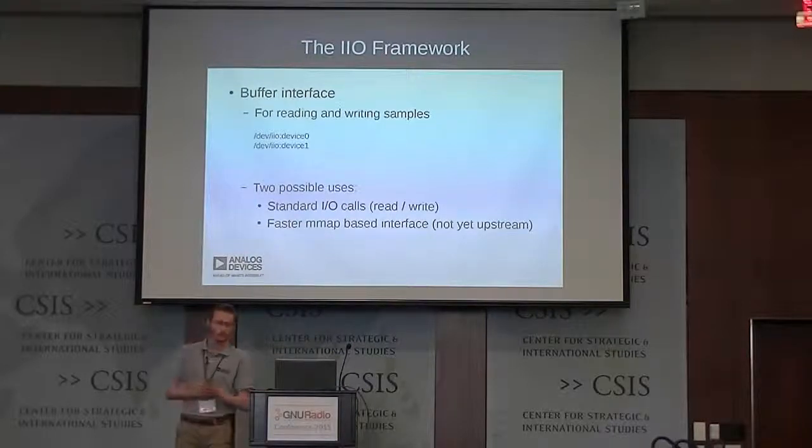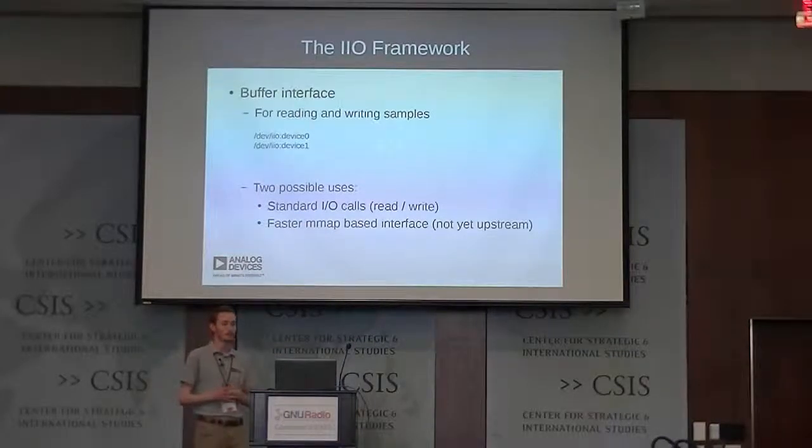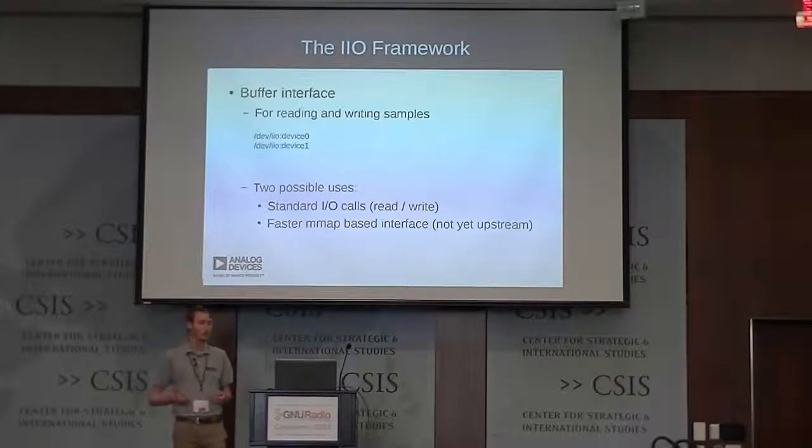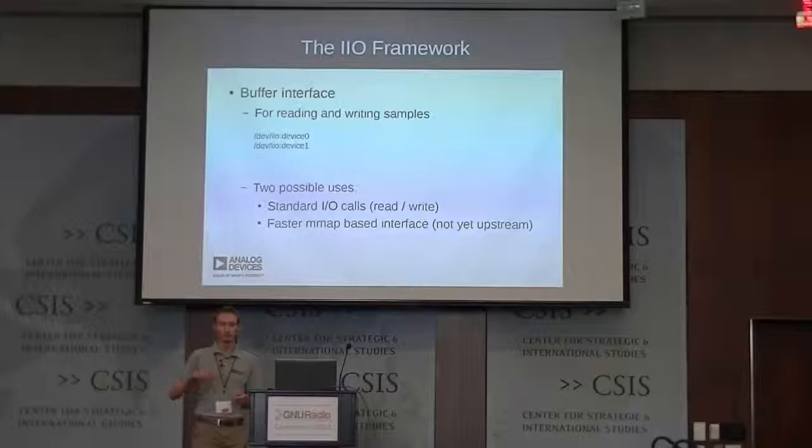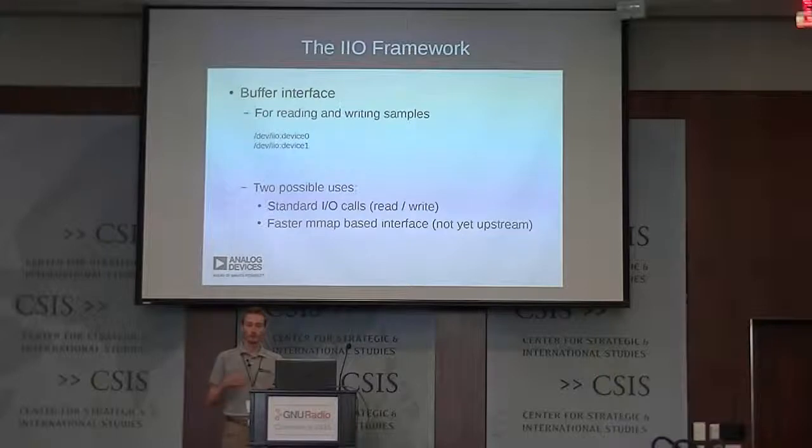There is a second interface that may or may not be used by all drivers, which is the buffer interface. That's a special node in the Linux file system where you will be able to read and write the samples. There are two possible ways of actually writing the samples, either using the standard IO calls, fread, fwrite, etc., or, only on the ADI Linux kernel, there is a faster way using advanced techniques.